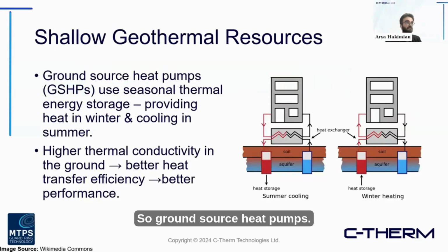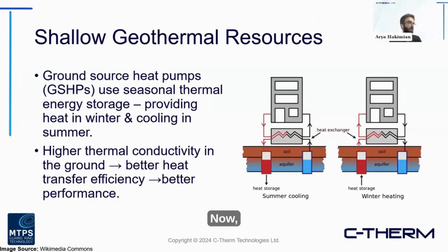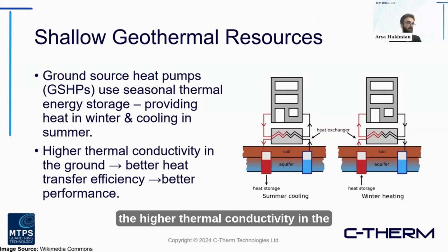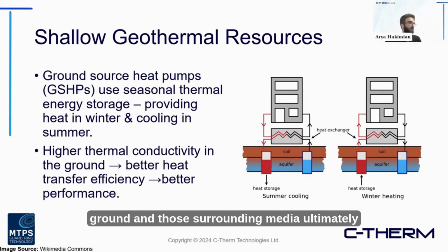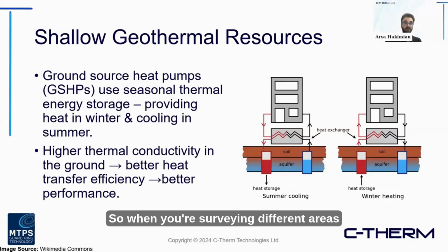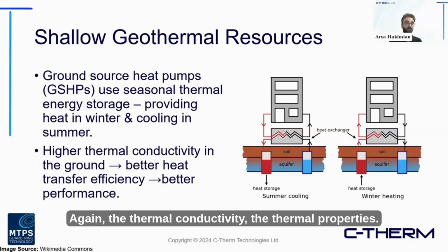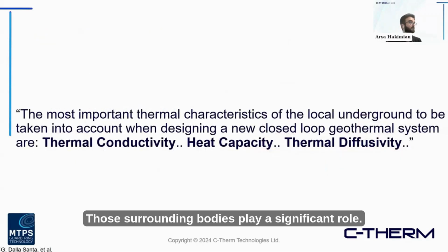So ground source heat pumps, these are again related to energy storage, thermal energy, providing heat in the winter, cooling in the summer. Now, the higher thermal conductivity in the ground and those surrounding media ultimately results in better heat transfer efficiency and better overall performance. So when you're surveying different areas to essentially assess the fit for these types of systems, again, the thermal conductivity, the thermal properties of those surrounding bodies play a significant role.